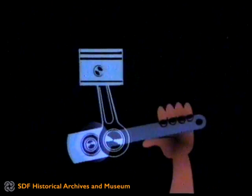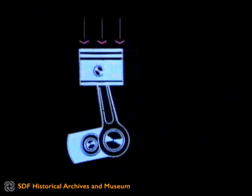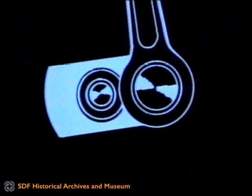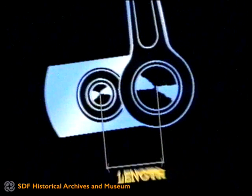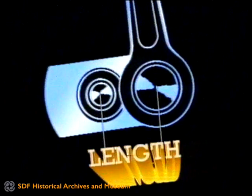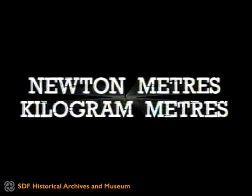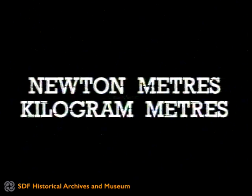The pressure exerted on the pistons by the combustion gases is picked up by the rod and, via the crank, causes the drive shaft to rotate. The engine torque is nothing other than the product of the force transmitted by the rod over the length of the crank. It being a question of a force multiplied by distance, the units of measurement of engine torque are Newton meters or kilogram meters.